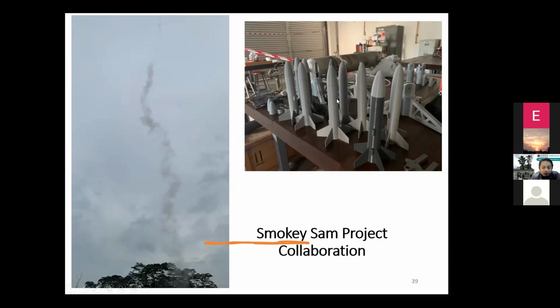That's why we are using a polymer, PLA, and we did some settings on the printing so that inside it is very hollow and very light. When it explodes, it will produce only small debris. This is one of the criteria from the company.